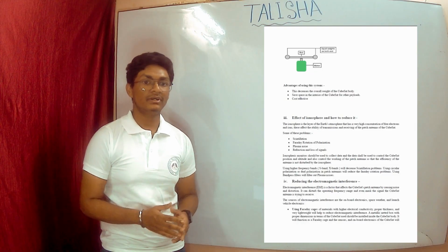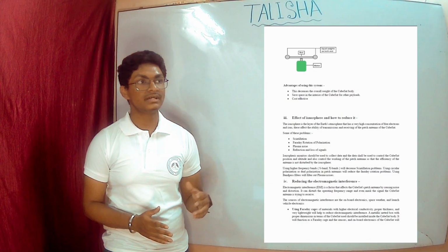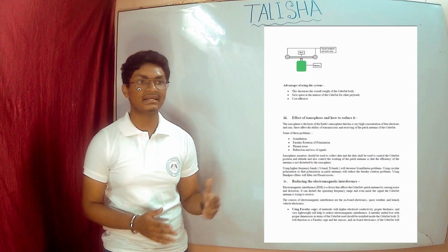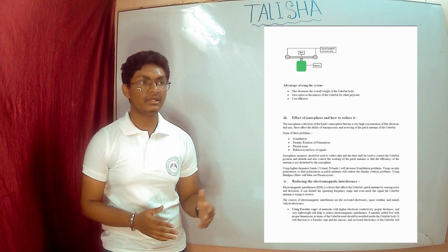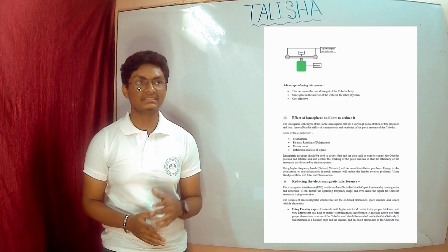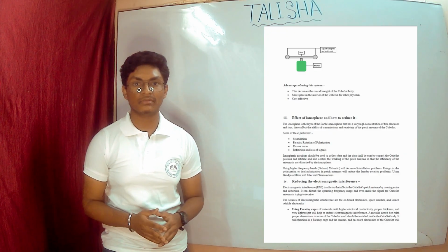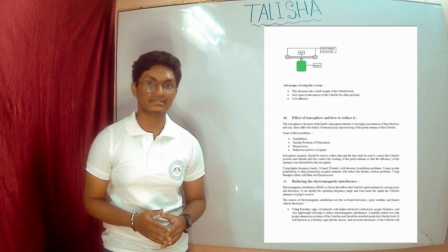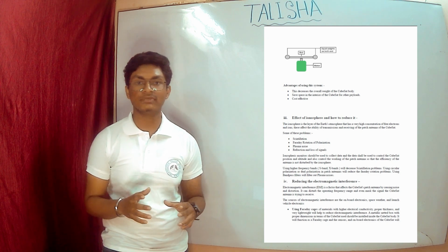So how to remove it? The traditional way of removing it is by using higher frequency radio bands, that is the X band and the S band, to communicate. So problems like scintillation will be removed. Now how to remove the plasma noise and the other problems? For plasma noise, what we can do is use Faraday cages, which will be installed inside the body of the Cubesat.